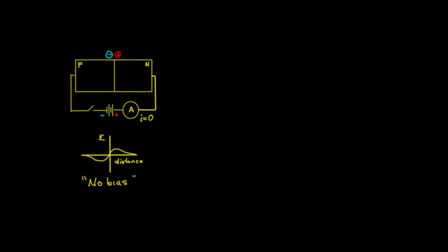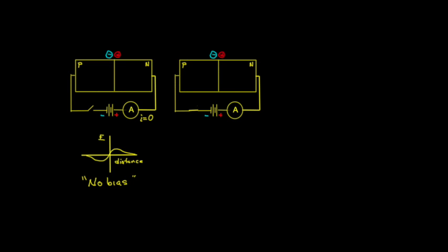If we close the switch, we find that the negative end of the battery is attached to the p-type material where negative charges already are built up. We are trying to push electrons into an area where an excess already exists. The potential energy barrier grows even larger. This situation is called a reverse bias condition. Consequently, little or no current flows.